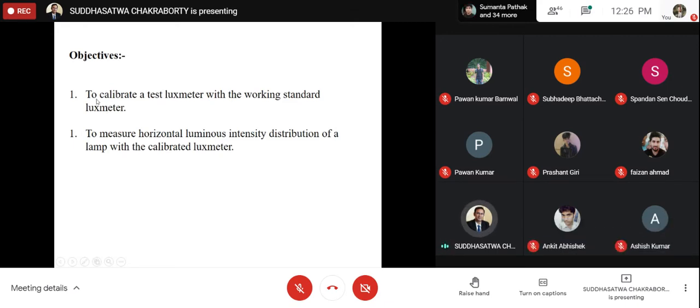We, the electrical engineers, and in fact all engineers, whenever we do any sort of measurement using a measuring instrument, the first step is that every time we need to check the calibration. No matter whether we are measuring voltage, current, frequency, power, whatever parameter, the measuring instrument is required to be calibrated before we start any measurement. That is a general standard practice we should follow.